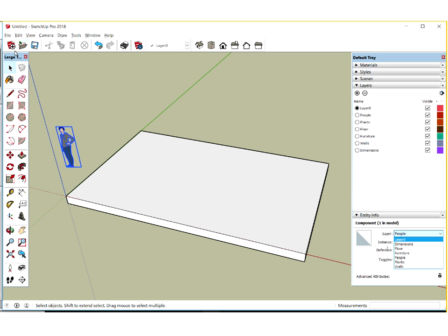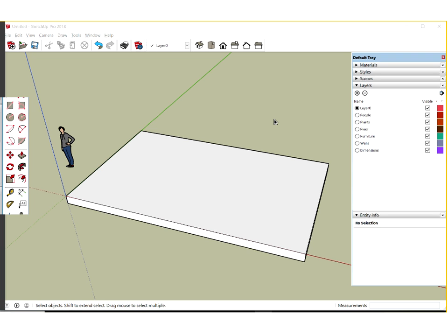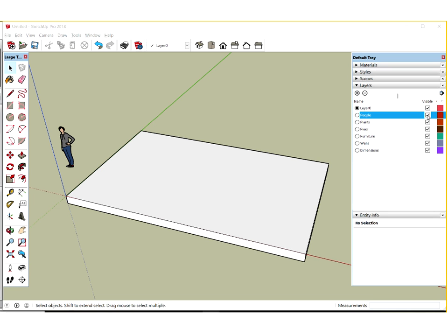What we'll do in just a second as well is create a couple of walls for our space here. So we'll use a couple of tools to do that. We'll be checking with accuracy. Modeling with control and accuracy is a key concept in SketchUp, so we want to make sure that we're on top of that. And once we've got items placed on a few layers, we then use our layers list to untick or tick layers to control their visibility. So I can untick the People layer there to hide Stacey, or tick it again.